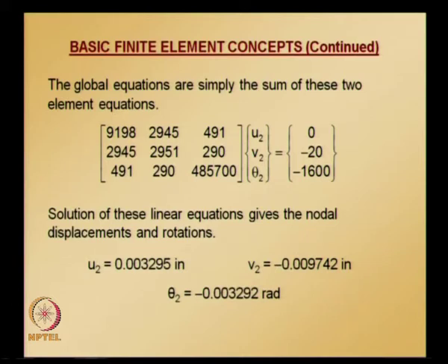Element forces can easily be obtained by first determining the local displacements, because whatever we calculated, these are all global degrees of freedom. We need to back calculate what are the local degrees of freedom or local displacements, and then using shape functions and their derivatives we can obtain what are the moments and what are the shear forces and axial forces. So let us go and do it for element 1 and element 2 separately.